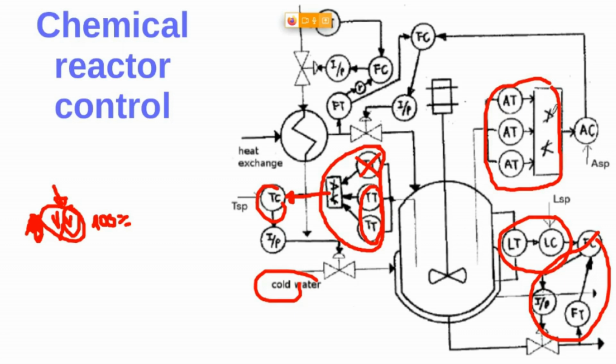And we don't take the maximum value nor the minimum value. So we can also figure out in here that we don't trust that all the measurements will be fine, will be right. So we assume that one out of these transmitters can fail. That's why we use 3, because 2 of them will give us the right value, right? For example, if you consider that 2 transmitters can fail at a time, you should use 5 transmitters, because 2 will fail, but 3 will give you the right measurement, right? If you take the one in the middle, for sure you will take a right measure.